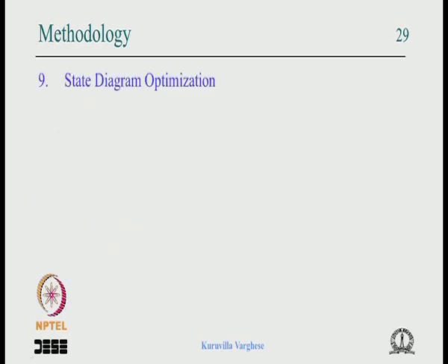In our case we didn't do much optimization, but there was one. If you remember, from the last state we said we could go to another state and make things inactive, then we realized that instead of going to a fifth state you can go back to the init state because those are equivalent. In a complex case this may not be obvious; you have a lot of states, and there could be some states somewhere in the state diagram which are equivalent and can be brought together.